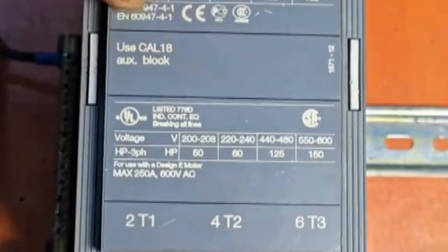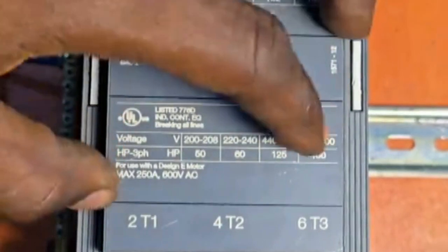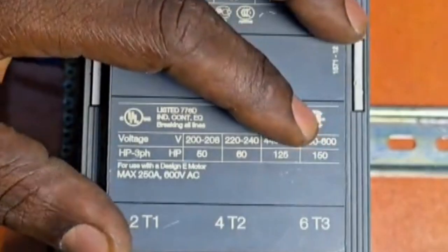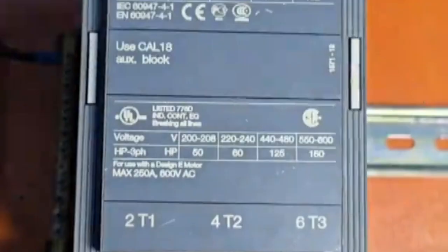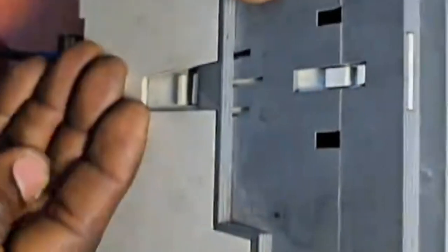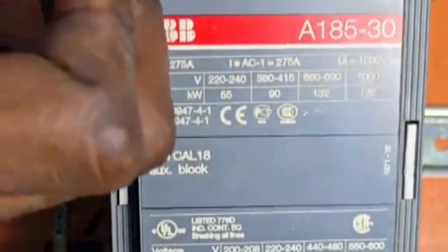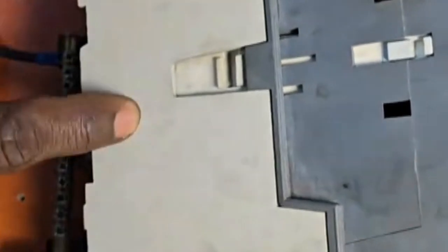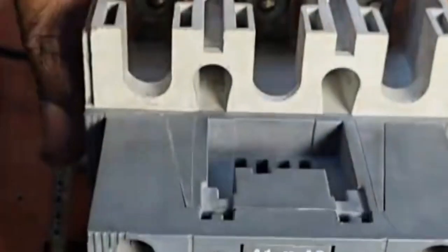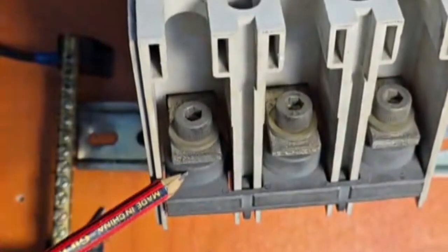You remember that I told you long ago that when you connect electricity to a coil of wire, that coil of wire will behave like a magnet. So inside this contactor, we have a coil at the base down here, and the coil terminals are A1 and A2. So when we connect this signal, the control signal, to these terminals, this coil, which is stationary down here, is going to behave like a magnet, and it will attract another moving part here, which will now make these terminals at this side to get electrically connected to these terminals on this side.